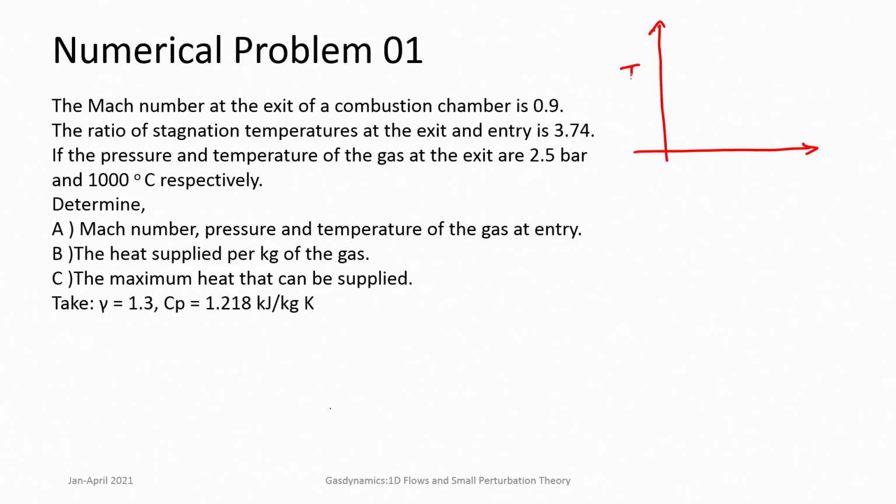So, if you can keep this in mind, this is the qualitative description of how a Rayleigh curve looks. Here the stagnation temperatures keep changing. So, one should look at stagnation points also, and there is a maximum entropy point which is for Mach number equal to 1, and there is a point where there is maximum enthalpy, or temperature T is maximum.